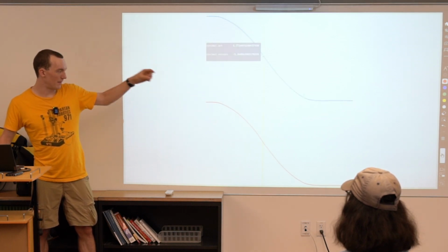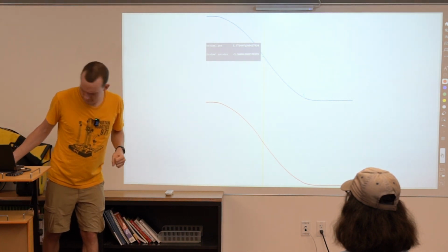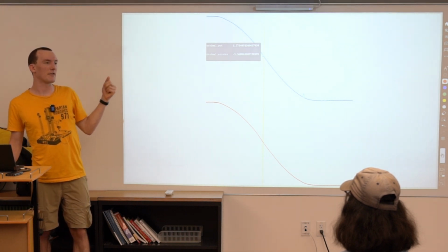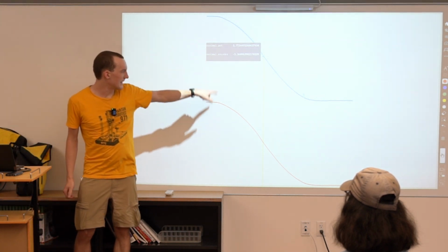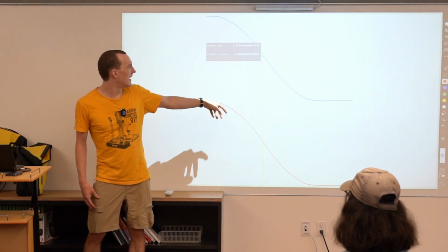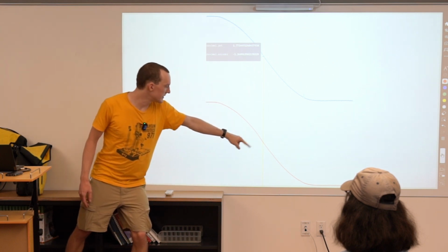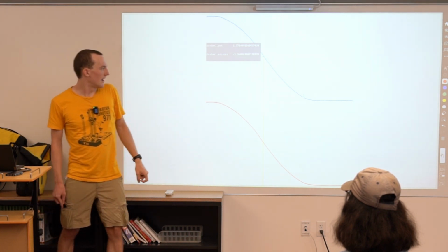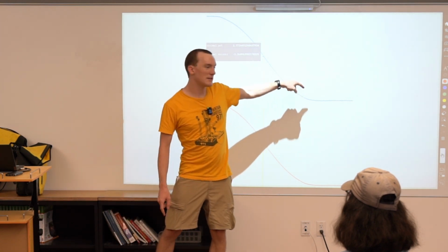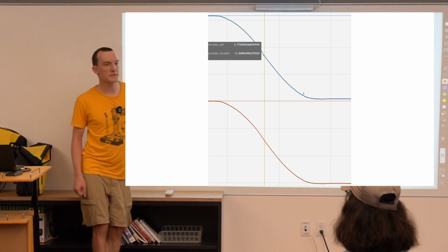As another example, this is a plot of some data that came out of our robot this year. This is just me picking a random log out of the robot. These are the same mechanism. They aren't on top of each other because of various reasons. The line on the top is a potentiometer. The line on the bottom is a quadrature encoder. And it's not perfect. You can see there are little blips in the potentiometer. I don't actually know what that little blip right there is exactly, but it can be due to electrical noise.